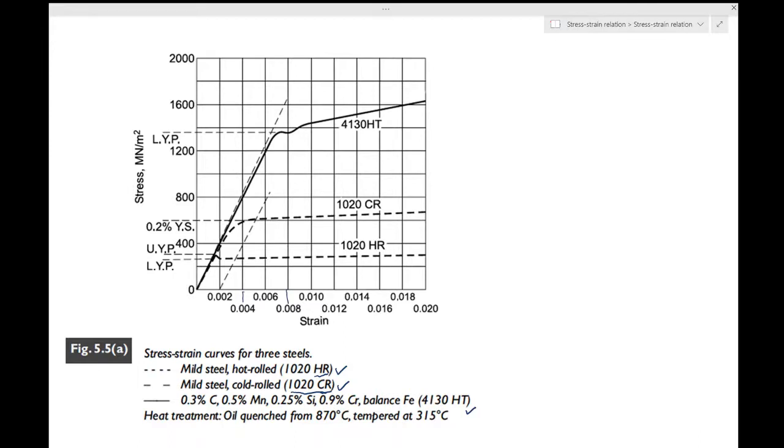Okay, there is a region for all three curves. These are the three stress versus strain behaviors, and clearly they are independent of your length and cross-sectional area, because you have plotted stress versus strain. If you were plotting load versus displacement, you would get a different curve based on what load and what area you had. Okay, fine.